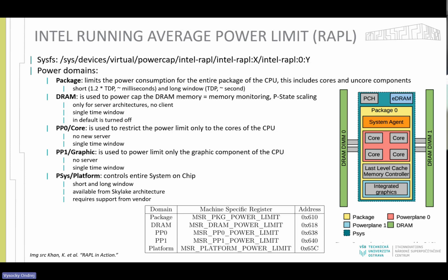It's important to know, because when you buy a CPU that has a TDP of 100 watts, or rather say 1000 watts almost nowadays, the power limit is evaluated for the package domain, while the DRAM domain is outside of that. So actually the CPU consumes even more than the TDP, but the TDP is specified for that one specific power domain, which is controlled.